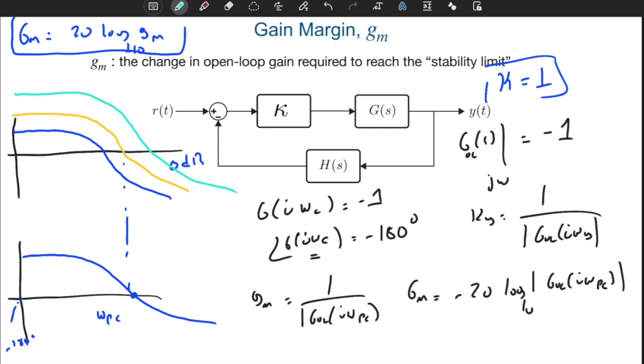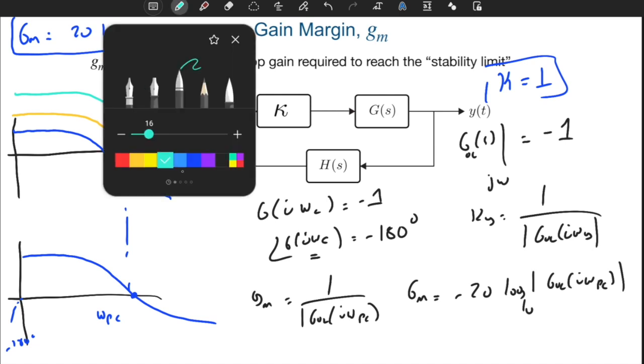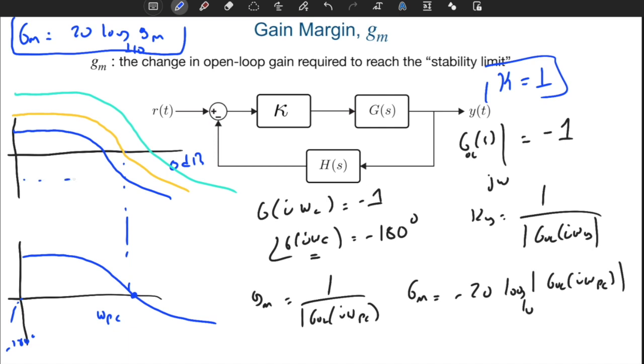So what I can do is look at the gain. Let's look at the first one. My gain is negative, but it's a logarithmic scale. It means that my current gain is less than the critical gain, because the critical gain is where I cross the 0 dB line. That's nice, which means that I'm stable.